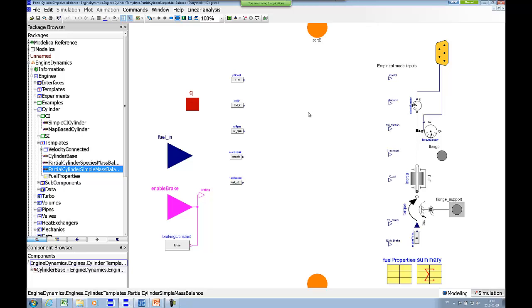It would be possible to have a neural network model or a regression model, for example, or linking in an external combustion model from a function. So what you need to do is to provide values for all the real input connectors on this right side. So you need to specify the volumetric efficiency, the energy conversion efficiency of the combustion, the friction torque, and the exhaust gas temperature. The remaining connectors are then optional.